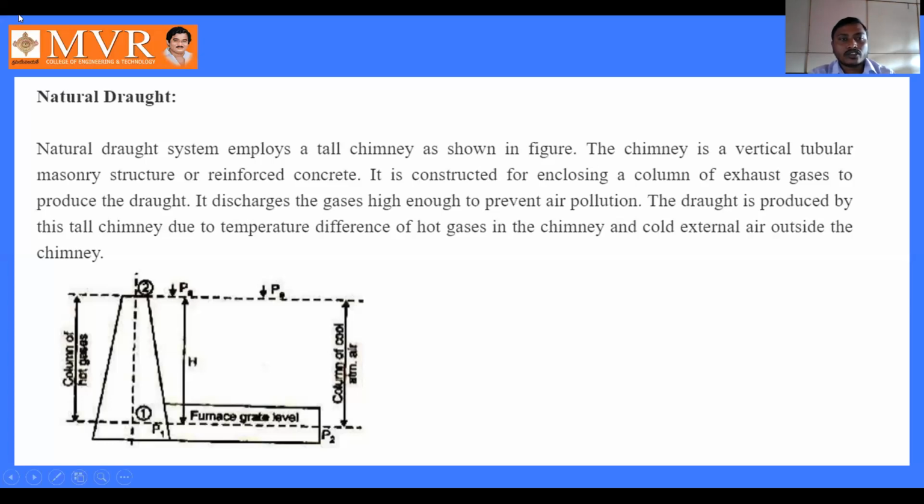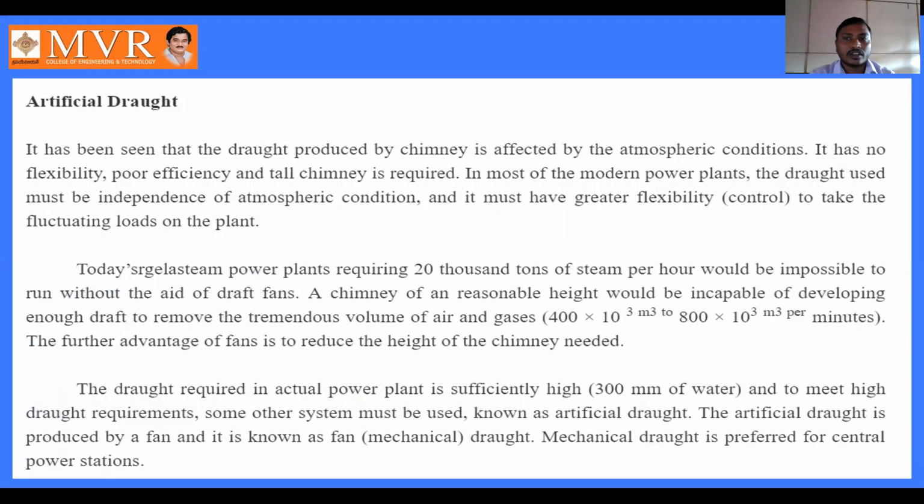From the name itself, natural draft, the draft is formed naturally due to the temperature differences between inside of the boiler and outside due to atmospheric conditions.